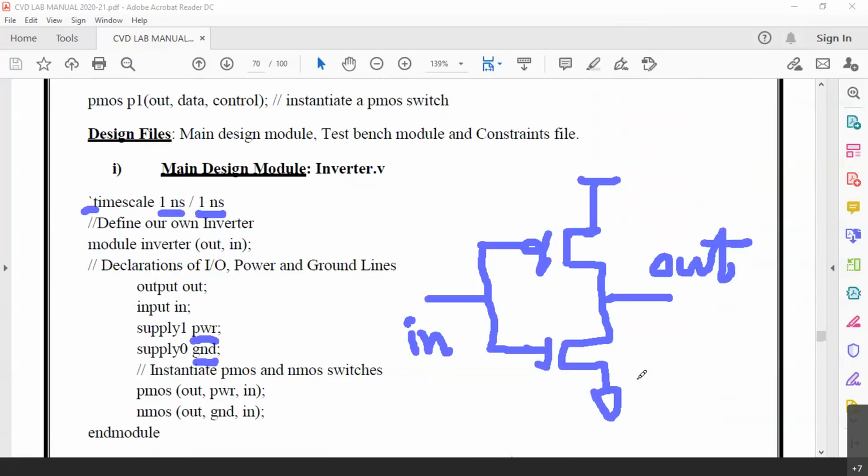But it is very much required in the analog domain, because analog domain is basically a full custom design. Full custom design in the sense, right from the transistor level, everything we do. Whereas in the digital domain, we cannot say that it is a full custom design. It can be a semi-custom design, where an inverter's complete description along with the layout can be available with the tool, and we can simply write a Verilog code to connect all those gates.